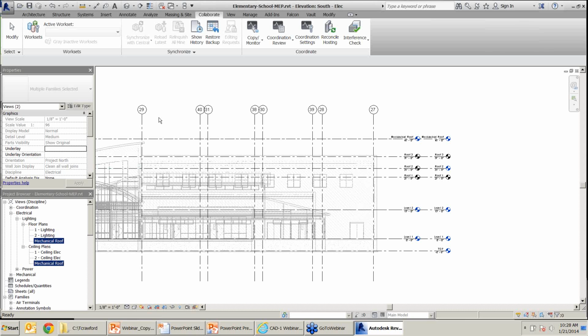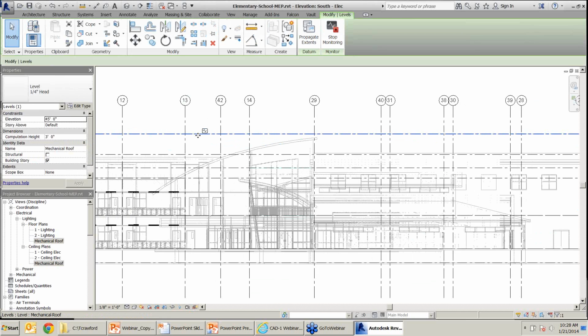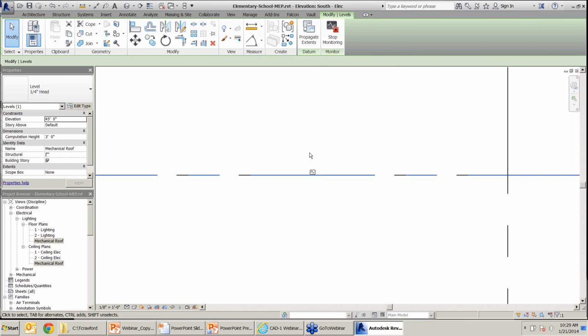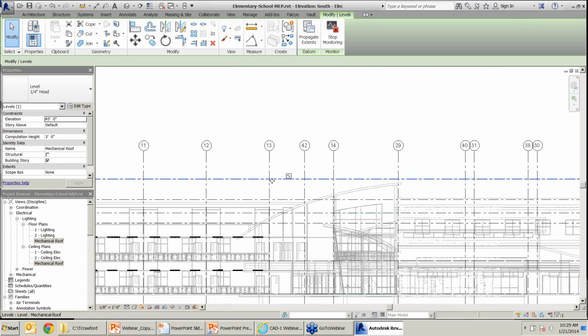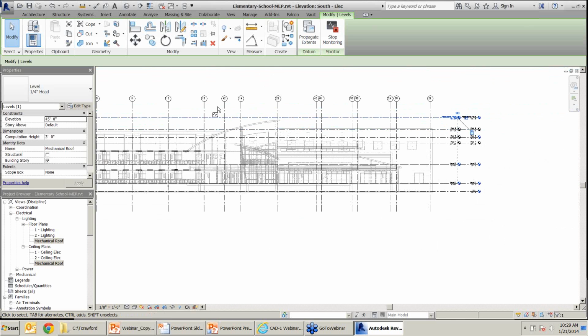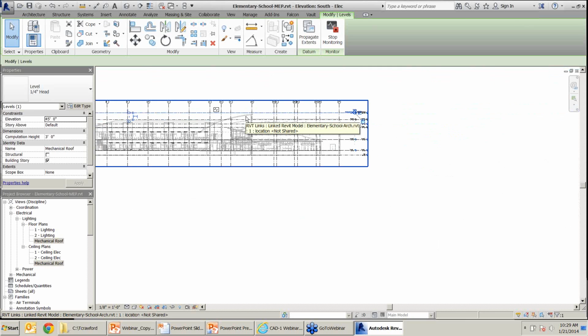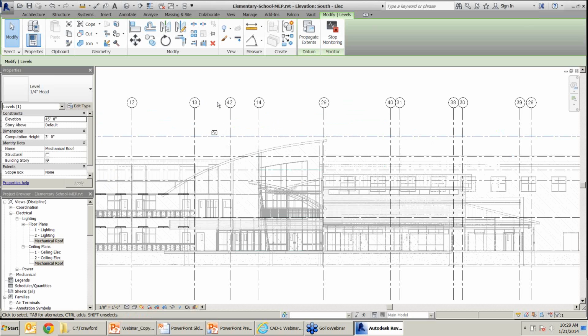The monitor. Juliana calls it the Harry Potter mark, monitor mark. There it is. And if I zoom in, you notice it does not get any bigger. The lightning bolt or the Harry Potter mark or the heart rate monitor. That's the way Revit works. A lot of these on-screen symbols, the temporary symbols, always stay the same size on the screen no matter how much you zoom in. So if you're having trouble selecting something, if you're coming from the CAD world, you might be used to zooming in. It might be counterintuitive, but sometimes in Revit it works better if you zoom out if you're having trouble selecting something. Sometimes.